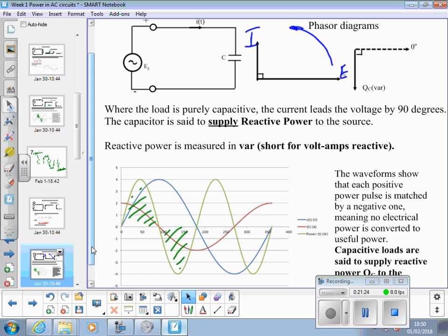If we had just an inductor and a capacitor, we'd have the power shunting between the two, because in one half cycle the inductor will be losing its magnetism and charging the capacitor up, and in the other half cycle vice versa. You have a current flowing backwards and forwards between the two effectively. Not quite achievable, but you can get close to it. You won't be doing anything useful except making inductors and capacitors hot. Alright?